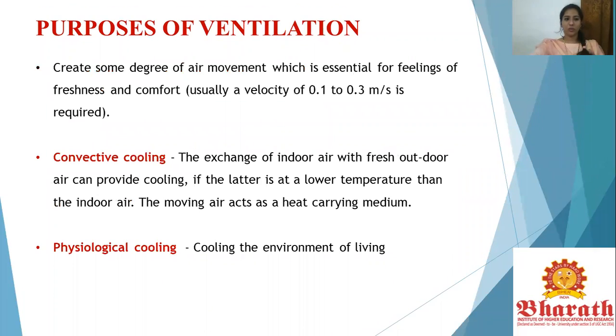The other purpose of ventilation would be to create some degree of air movement, which is essential for feelings of freshness and comfort. Usually a velocity of 0.1 to 0.3 meters per second is required. So it's talking about how a degree of air movement is required, the feeling of fresh air on your face and all of those such elements.